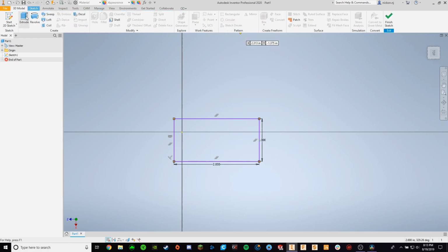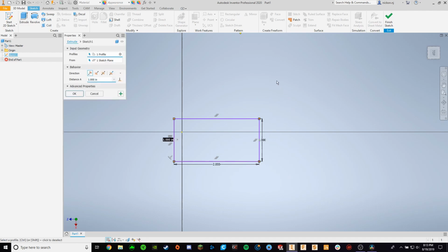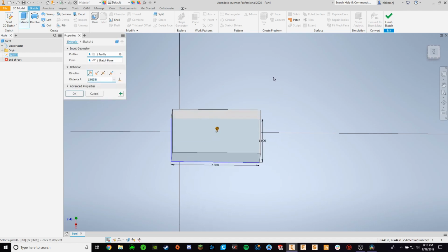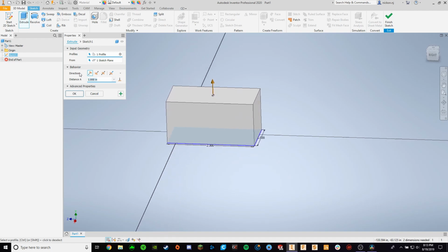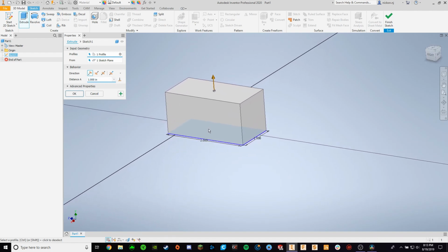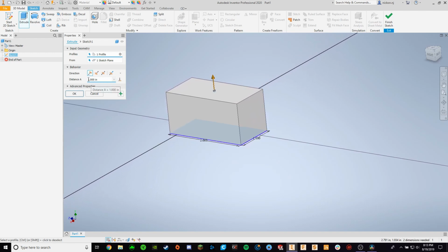So check out the 3D model tab and you'll find this really nifty tool called extrude, and an extrusion is a type of feature in Inventor which is going to let us effectively set a height for our prism. So if you press extrude, or you can press the E key, you see this dialog box that wants us to select a sketch profile, and if we click inside of our little box, you can see, boom, now we've got a box.